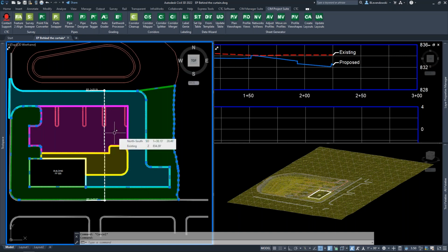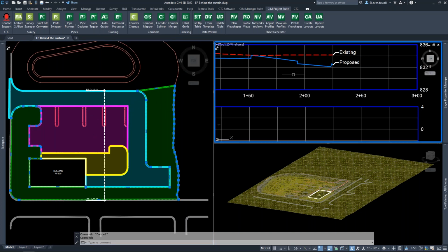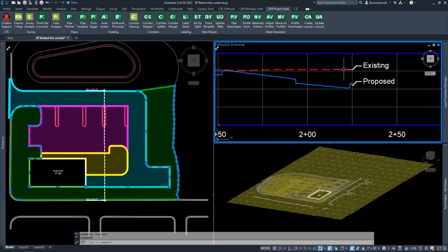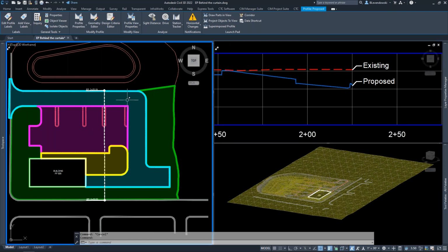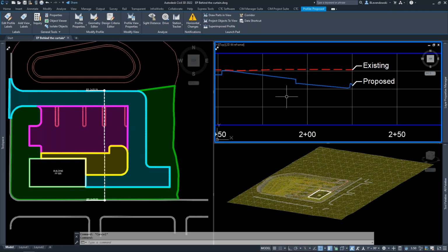And so what I'm after to calculate my common earthwork is to be able to generate a surface that is a variable depth across the site. If I look over here in my profile views, here's my existing, here's my proposed. My subgrade surface would be some distance below this, but the depth would vary depending on these different areas. This is a simple commercial building site example, but it applies to all kinds of road work where corridors won't meet the grade, or residential projects, or you name it, lots of different applications. This is just the example we are taking today.